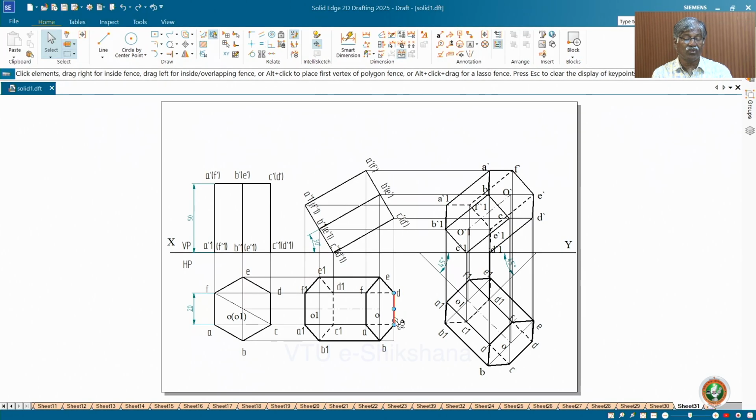Now what happened to this axis from O1 to O is apparent length. So find the apparent inclination using the true inclination 45 degree and the apparent length, this you get beta. So definitely you get 55 degree as beta. You can try, and then on that 55 degree you must keep this O1, and whichever the orientation you want, top face towards you or base towards you, and get the corresponding final front view and top view. So that's all about the hexagonal prism.